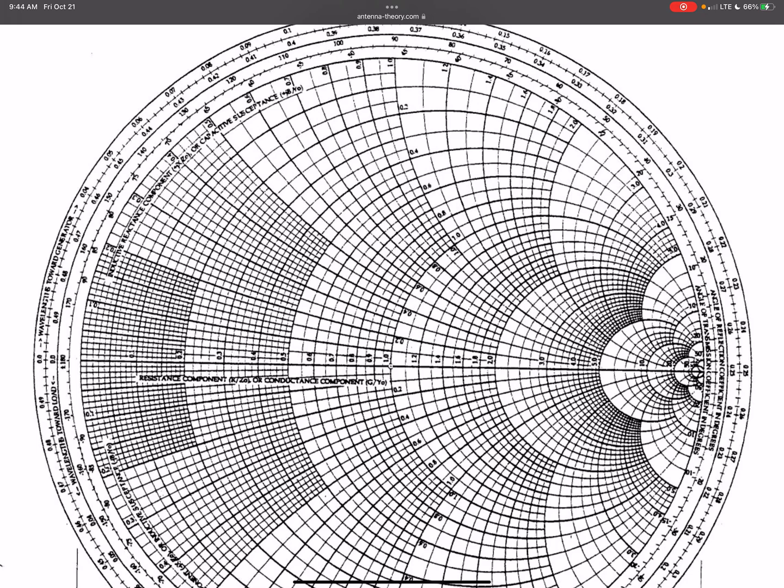And then we can draw a line showing how that point moves around as you move away from the load, as you go along the transmission line. From then on, you can just read off your effective impedance looking into the transmission line just by looking at the graph and not needing to calculate those tangent, delta, whatever. And it also gives you a feel about what's going on.